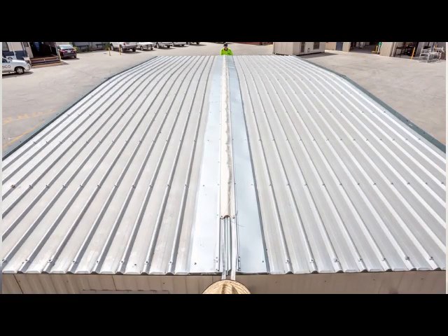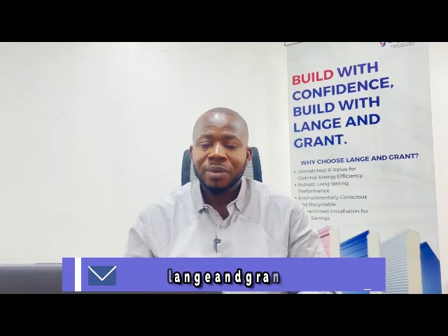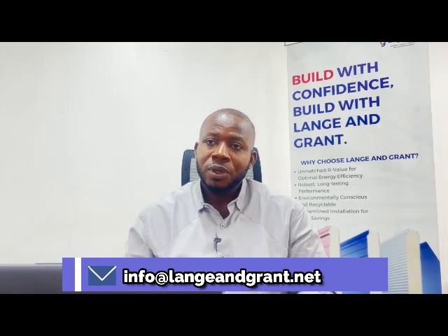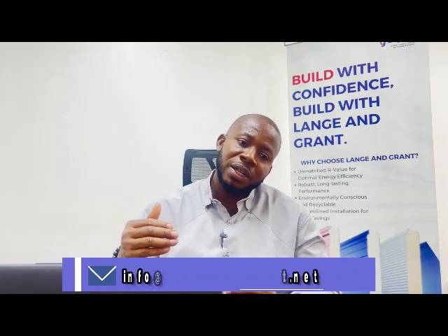So we use our fasteners and rubber gaskets to ensure that every space is properly sealed. There is no water ingress or there is no risk of leakage in the future. Lastly, we will apply a butyl or a sealant tape at the top of the roof. This is also to prevent leakage and to ensure that we don't have any leakage problem in the future.